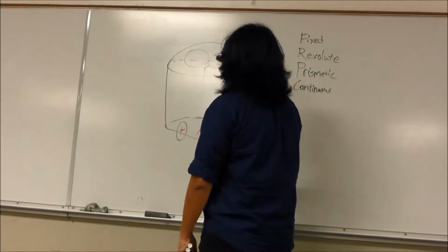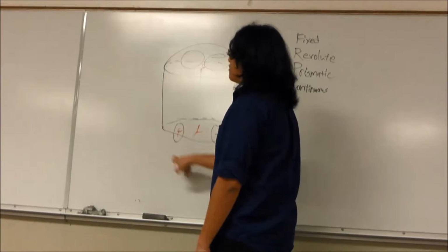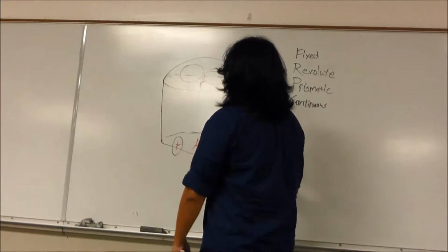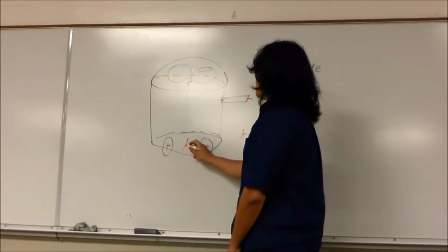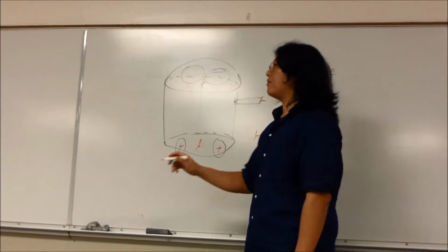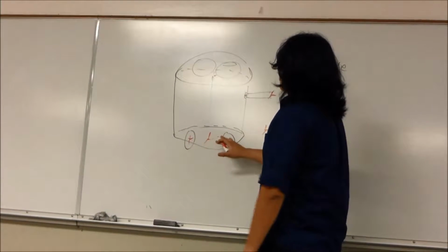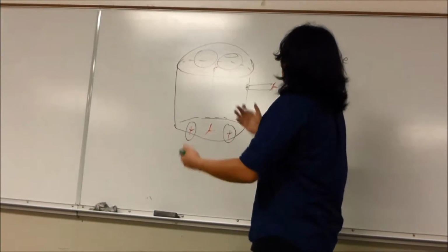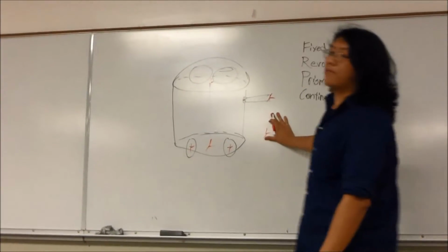So there could be a frame somewhere attached to the world, and as his drive wheels move, his base frame moves relative to that world frame. And we use the term odometry to refer to your robot's perceived position in the world relative to some fixed world frame.